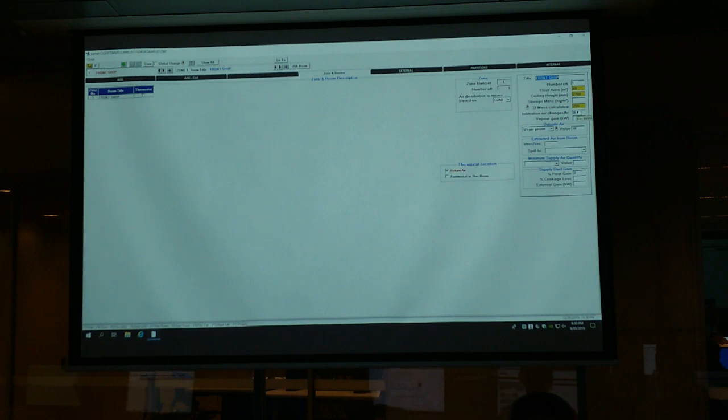You don't have to do anything; you can just leave it like that, point 4. But you need to input the fresh air volumetric flow rate. You can input by liters per second or number of air changes, can be fixed or can be based on